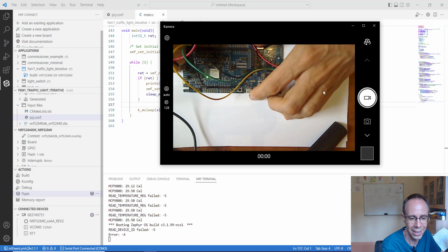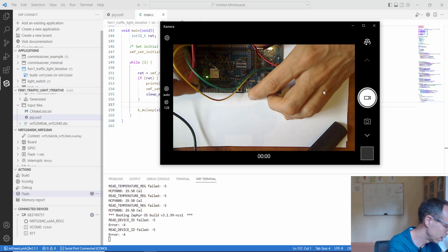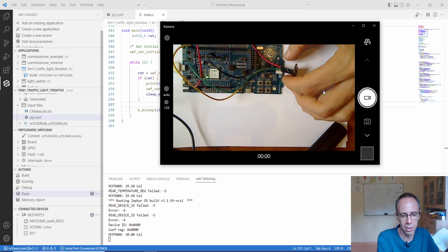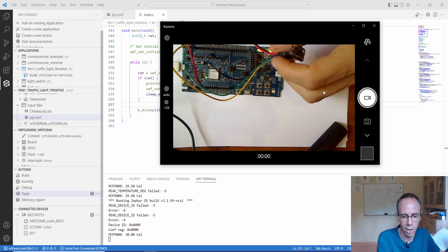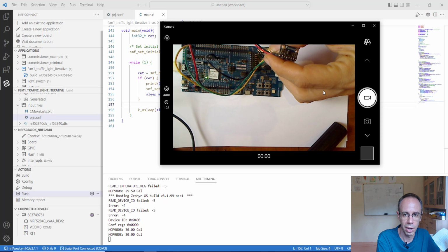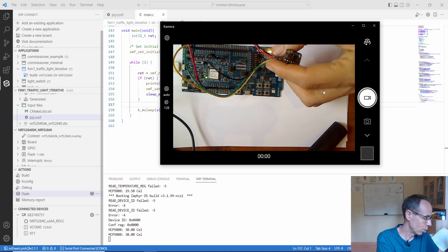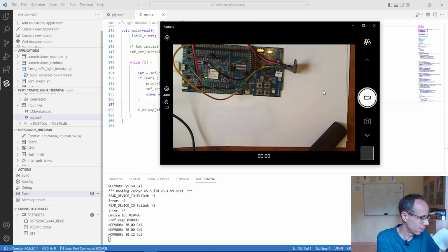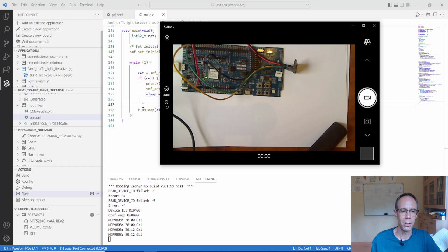You see our error handling here. The device ID is not ready, but I can plug it in again because the state machine starts from the beginning. So I plug this in here again, and then it reads out the sensor again. And there I can always do error handling. Of course, when our sensor is fixed on the board, the probability is not so high, but when we're working with cables it can always happen, and it's always good to do some kind of error handling there.